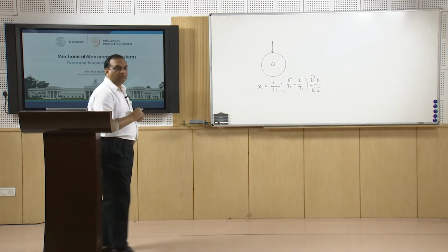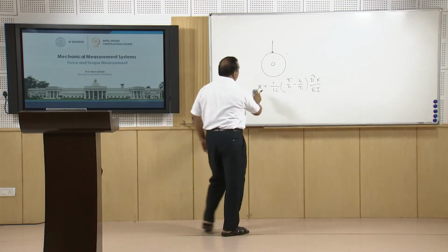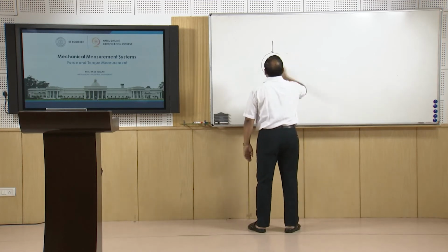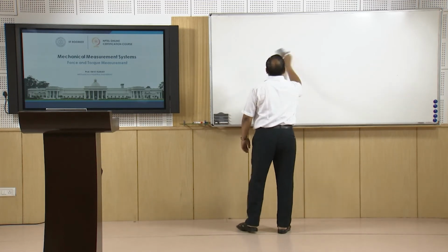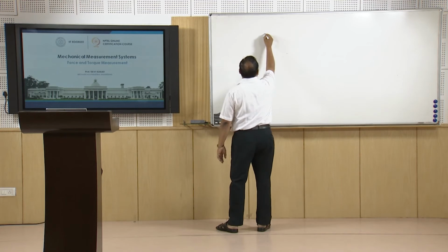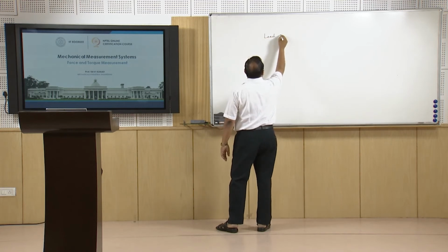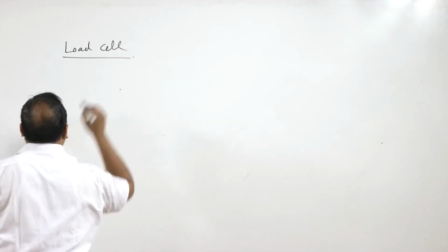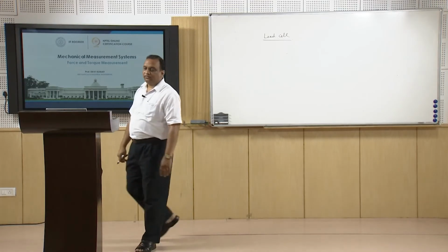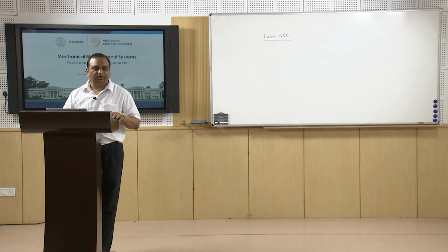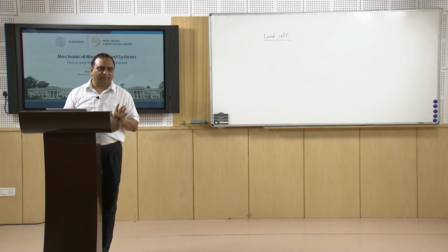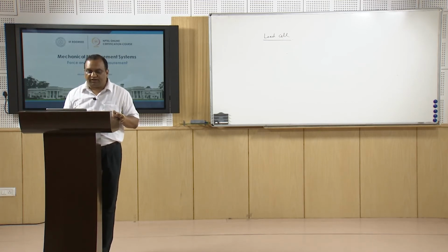There are load cells also. Load cells are very popular for force measurement, and they have a variety of applications. The load cell is used to describe a variety of force transducers which utilize the deflection or strain of an elastic member, or the increase in pressure in a closed fluid.